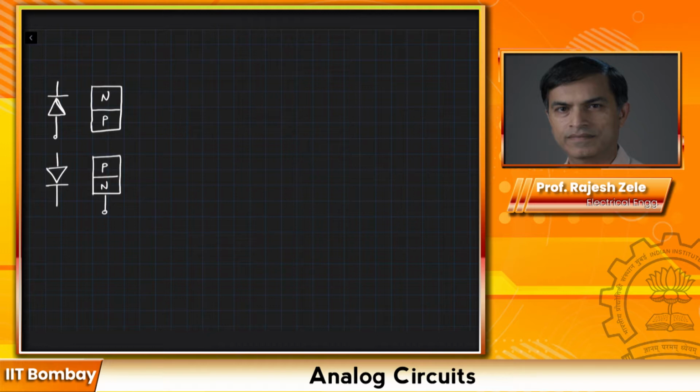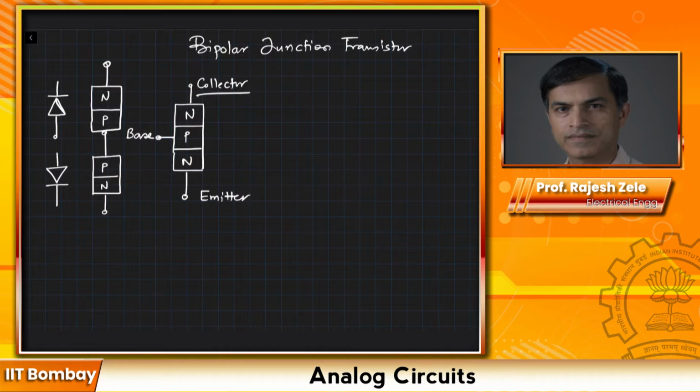Now we merge these two P regions and we make this NPN transistor. So let's redraw the combo sandwich, and it looks like this. You have N, P, and N. The region on the bottom we call the emitter, the one in the middle we call the base, and the third one on top we call the collector. The emitter has the highest, heavy doping.